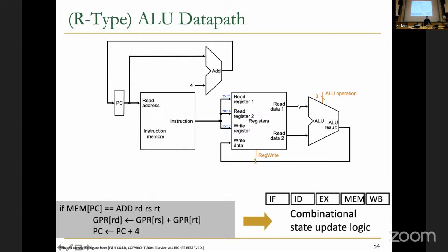And then we basically got the data out in this data path, and now there's an ALU. The question is, what should the ALU do? Well, there needs to be a control signal that's controlled appropriately. And so we need to generate a control signal that says ALU should do add. We'll see how it's generated, but you will see that later. Basically, this control signal should be set to add, and then the ALU provides the result, and that gets connected to the write data port.